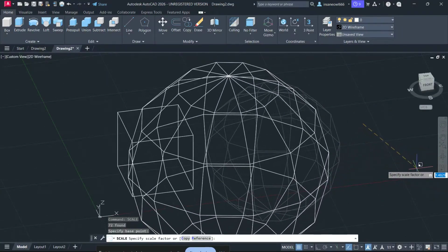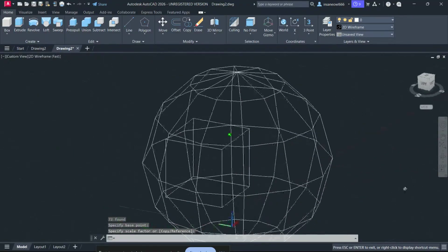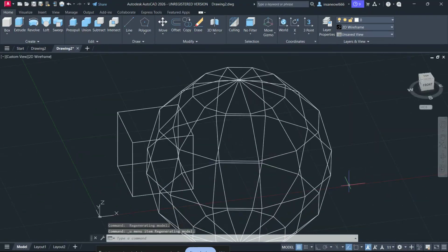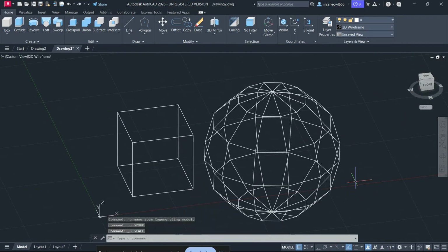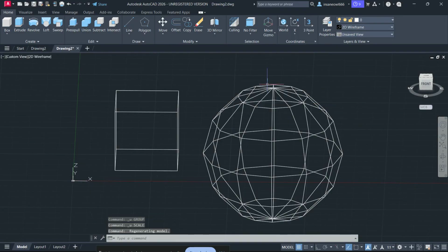If you're working with imported files, it's also worth checking whether the problem started during conversion from another software. Imported solids can carry hidden issues that don't show up immediately. In that case, the micro move, clean body, and incremental union steps become even more important. The key is to make the object mathematically simpler and more stable before asking AutoCAD to perform a Boolean operation.